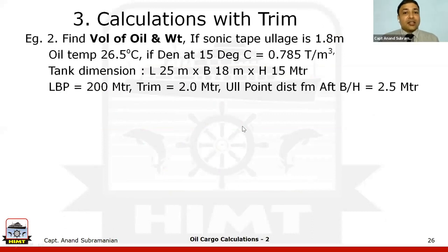So, sir, one question raised by Mr. Sahil. Explain how to find VCF. Yes, the VCF was taken up in the first class. Last class I showed you a screenshot of the VCF tables, and how to access it using the observed temperature and the density at 15 degrees Celsius.